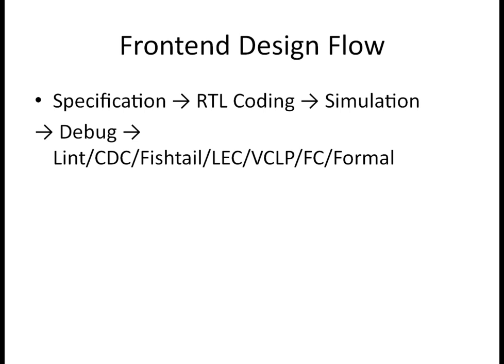Okay, so here again the input will be your RTL, your timing constraints that are coming from the designer, and if there is any hard macro in the design, for that we'll be using .libs. And if there are some standard cells we are going to use, like your AND gate or OR gate, or some memories, like FIFO and all, in that case we'll be using standard cells, and we can directly instantiate them in the design, because as this is a standard cell, we don't have to write it in the code. We can directly instantiate it in our code. So those will be our inputs for the tool.